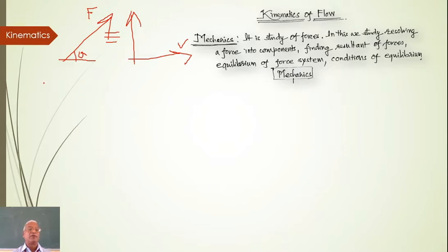And then if you have a number of forces, how to reduce them into a resultant, like you will be doing sigma Fx and then sigma Fy. Using sigma Fx and sigma Fy, you will be finding out the resultant and inclination of the resultant with one of the references as alpha.